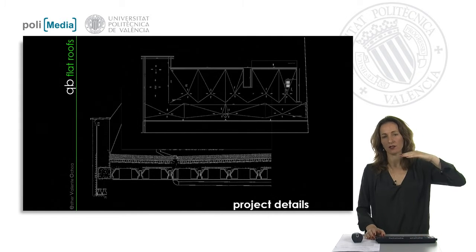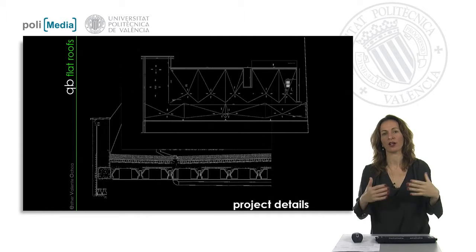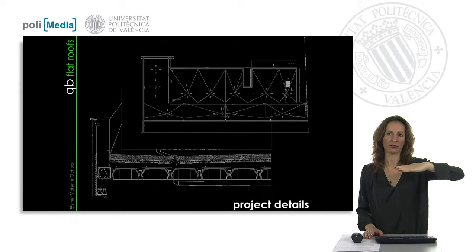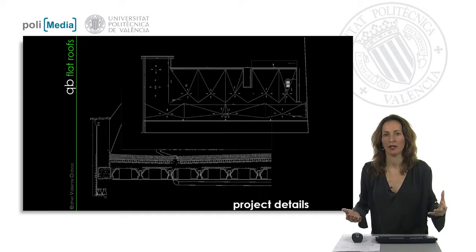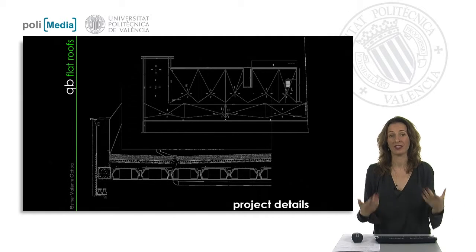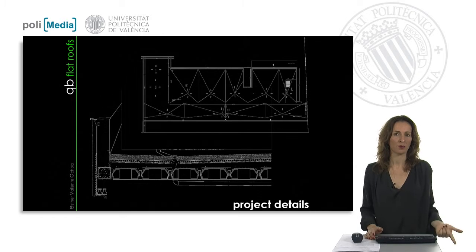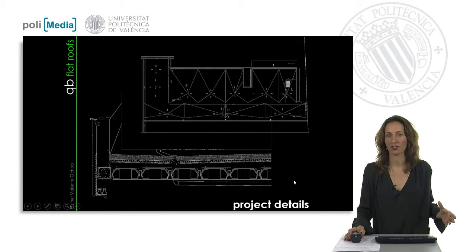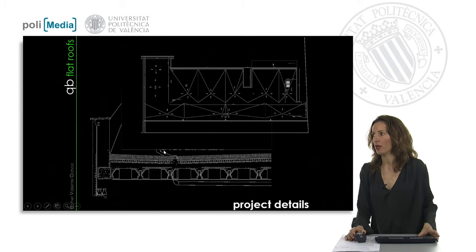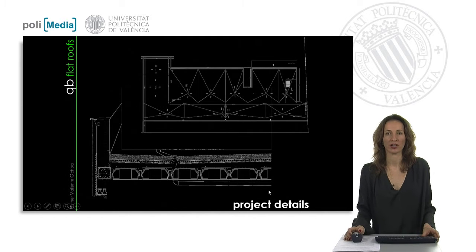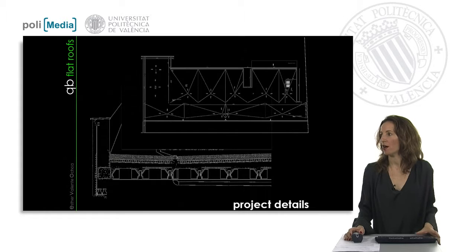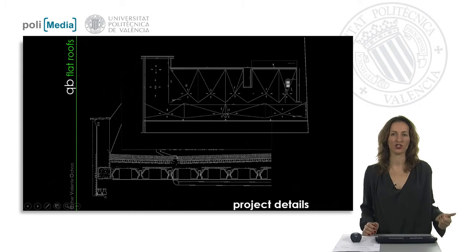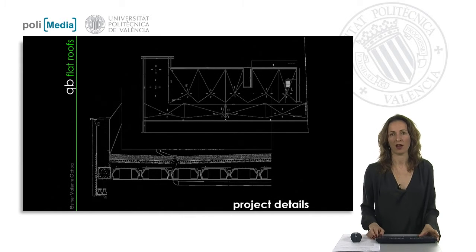Roofs are the skin, the horizontal surface of our buildings, so they are the elements that protect the whole building. Whether we have flat roofs or pitched roofs, we have to be open-minded, because between both systems there are different solutions depending on the designers and the providers of our materials. In this detail we can see a horizontal surface in the structure holding the flat roof. Right here you can see the position of the drainage system for the waterproof drainage, and of course several sheets composing our roof in order to resolve the insulation and waterproofing requirements in our flat roofs.